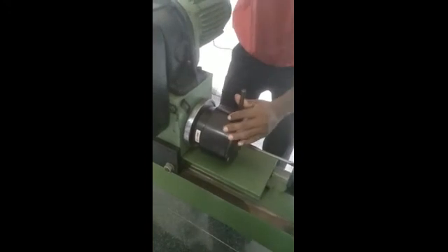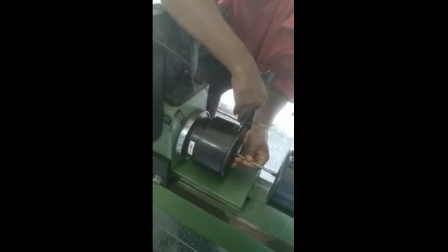We have to open the jaw, insert the specimen, match the pointer with the center drill, and tighten the jaws. Both the jaws have to be tightened. This is the method of fixing the specimen. First insert one side, then match the pointer with the center drill, then tighten the jaw. Then come to the second side, move the setup forward, match the pointer with the center drill, then tighten the jaw.